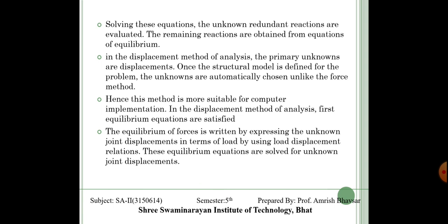In the displacement method of analysis, the primary unknowns are displacements. Once the structural model is defined for the problem, the unknowns are automatically chosen, unlike the force method. Hence, this method is more suitable for computer implementation.